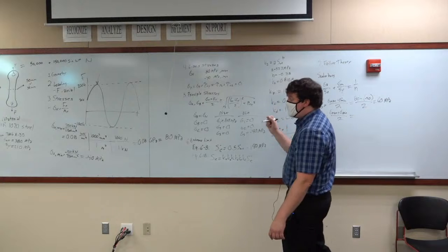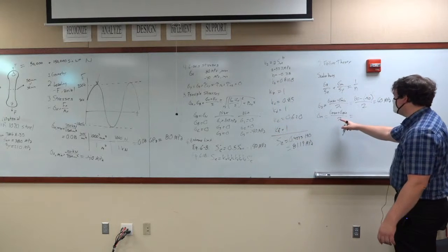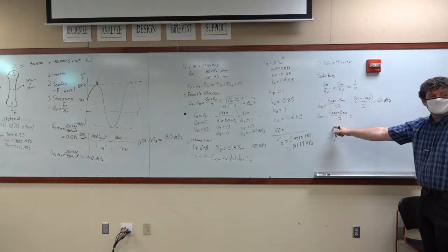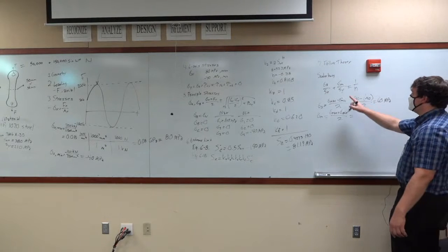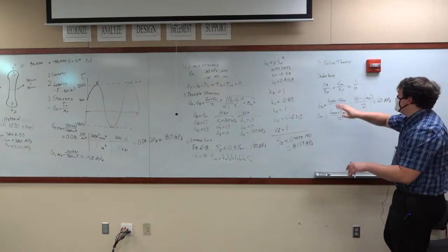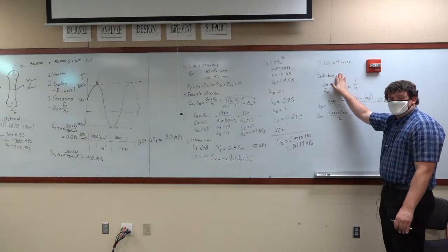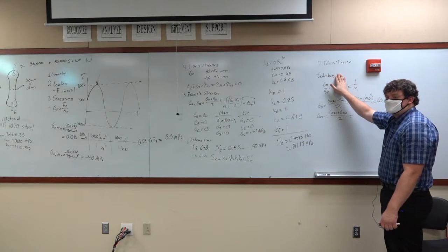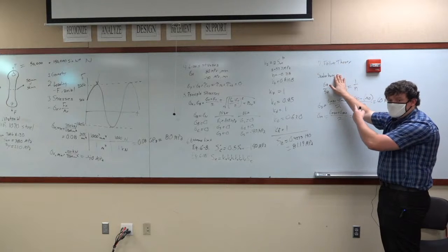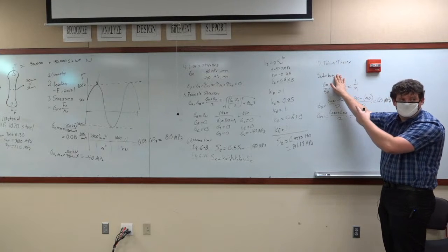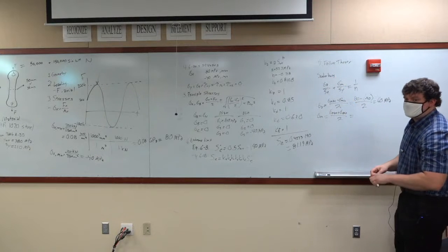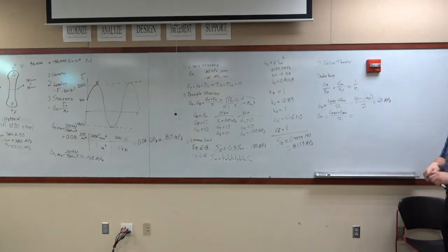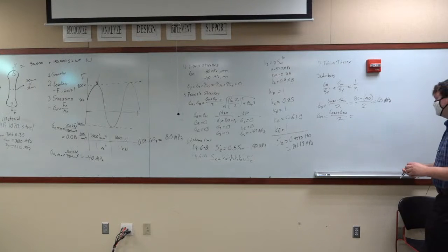Your sigma m value would be 0. It is oscillating about 0. If you plug it into the Soderberg equation, that term goes away. And the equation I gave you for fully reversed loading is the Soderberg equation, just with sigma m equals 0. That's why I specified in that lecture that it was only for fully reversed loading, because we hadn't gotten into this material yet.